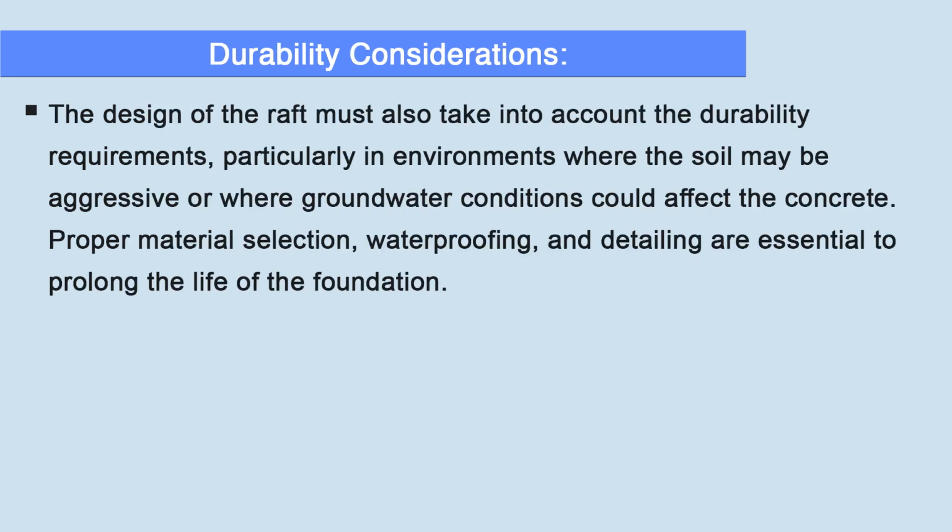Then the next is durability considerations. The design of the raft must also take into account the durability requirements, particularly in environments where the soil may be aggressive or where groundwater conditions could affect the concrete. Proper material selection, waterproofing and detailing are essential to prolong the life of the foundation.